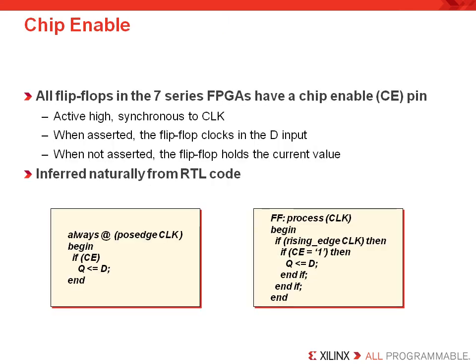Now, this example is a good way to code for your FPGA's flip-flops clock enable port functionality, and as you can see, this is easily inferred using standard HDL coding practices. So you're simply going to have your clock enable not in your sensitivity list, first of all, and it will be placed in your secondary parenthesis to define the actual Q to D behavior of the flip-flop.